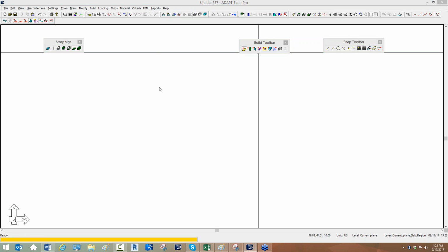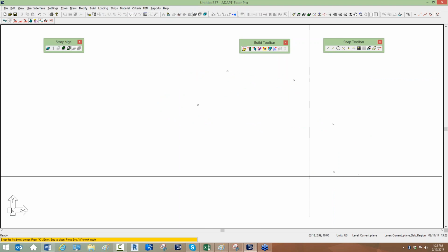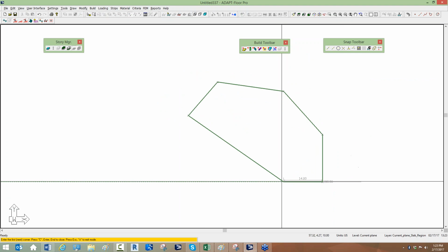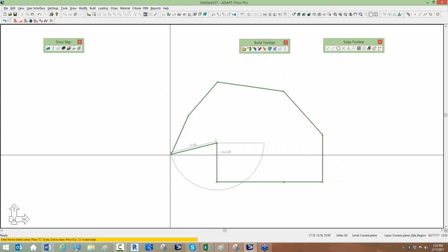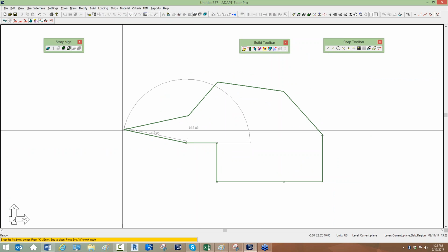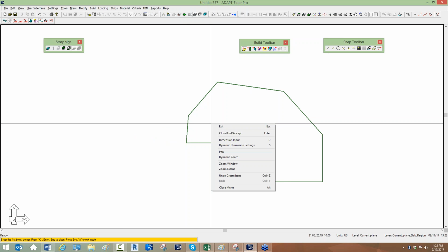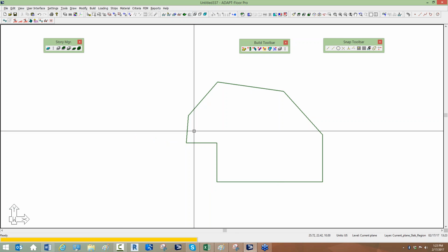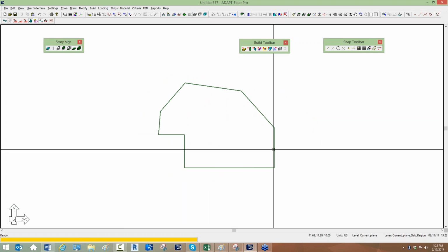If I go ahead and create a model, some of you may have used our undo redo buttons, which unfortunately have not functioned great in the past, and we'll be forthright and upfront about that, but we've done a lot of work in just cleaning some of the basic modeling functions up in the slab. Now if you press enter, you can close a polygon. In previous versions you had to right click and close. Enter works for any polygon. You can also, if I wanted to undo, I can just simply undo the slab, redo, undo, redo, and so on. I could also backspace.